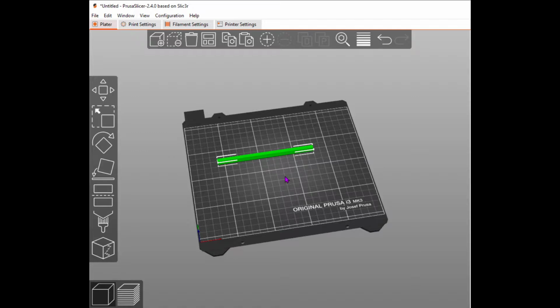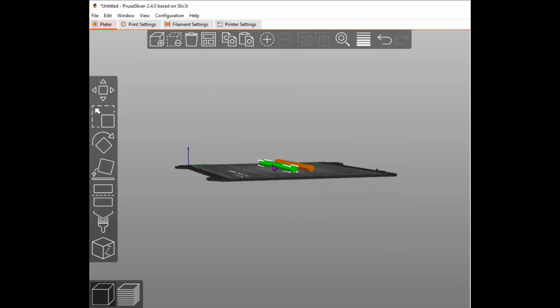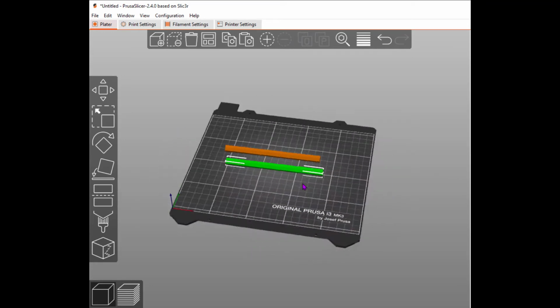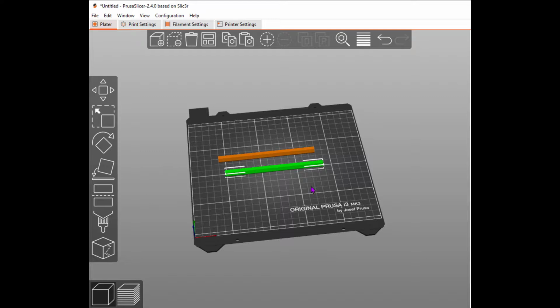The other thing you can do, because PrusaSlicer is pretty Windows compliant, is you can Control C, Control V, and you can generate a second piece here. So if you look at them, they're both laying flat on the heat bed. Both have a pretty high probability of adhering during print. However, if one of these detaches during print, you'll probably lose both of them. And because of their shape, if you lose either one with the other one following suit, because you can't print in midair, you probably wasted a fair amount of filament and a fair amount of time.